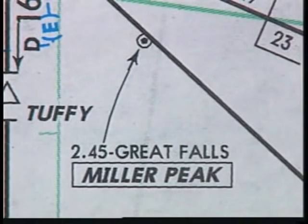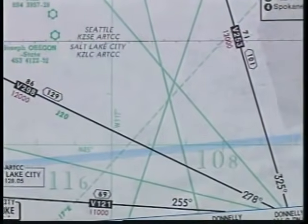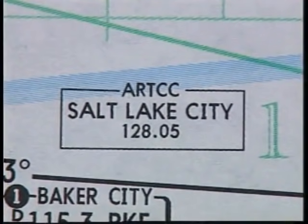The small encircled dot shows another en route communications service. The Great Falls FSS transmits and receives on 122.45 at the Miller Peak Remote Communications Outlet, or RCO. The black ticked line signifies the boundary between Salt Lake City Center and Seattle Center. You should expect a frequency change near this line. Boxes containing ARTCC frequencies can also be found throughout the charts.